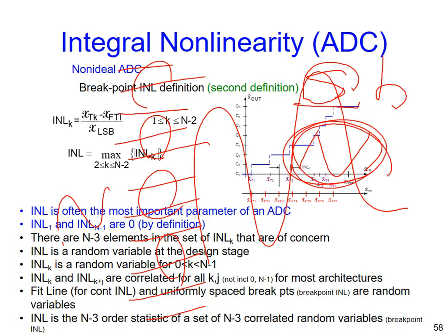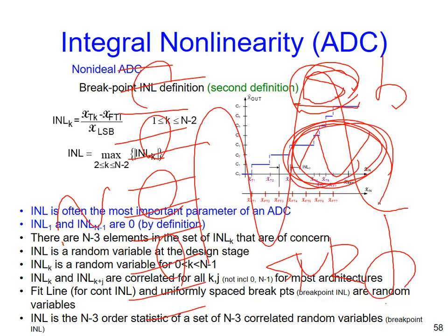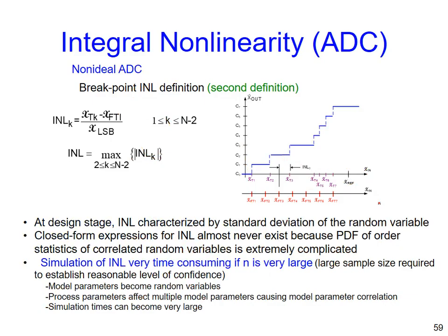Okay? So if you reduce the magnitude of your input signal, the result is your SNR will also be reduced because the quantization error is still the same. So we reduce the input signal a little bit, but not too much, for measurement. That is, again, the ugly truth. Okay, you need to face it. Don't try to get the maximum input signal. It doesn't make any sense. It will cause a lot of other problems.